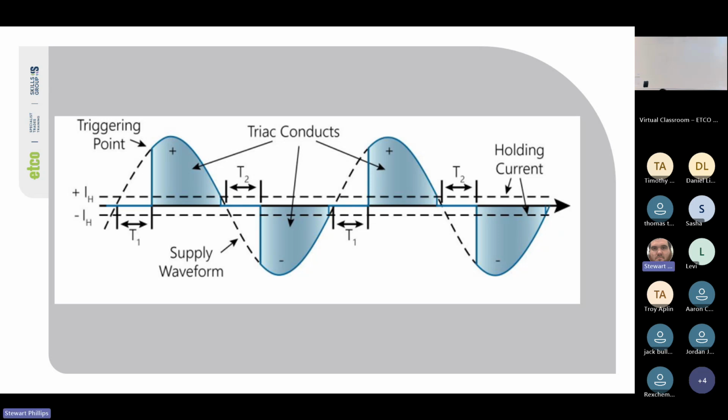So this is how we can use these two electronic components to dim circuits, which is why we need to make sure that we disconnect the dimmers before we do any insulation resistance testing, because they are not DC devices, but they are sensitive electronics. So it will not hit a transformer before it gets to these electronic components. That's why anything like a dimmer or electronic components that work on AC, we need to disconnect them.